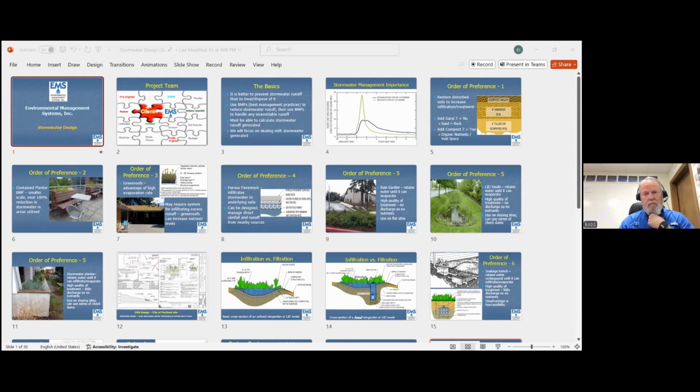You're going to start, typically, by looking at a lot of the mapped resources: the aerial photographs and topographic maps and soil maps and geologic maps, tax lot maps, all those kinds of things are going to come into play when you're trying to do planning on a site. So what is the community? What are the nearby water bodies that you're going to be dealing with? And taking all that into account.